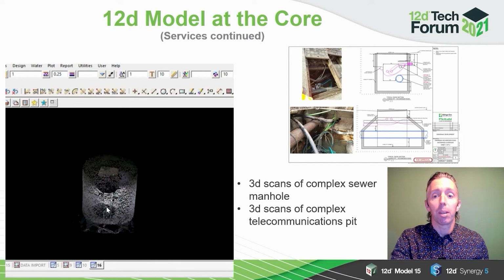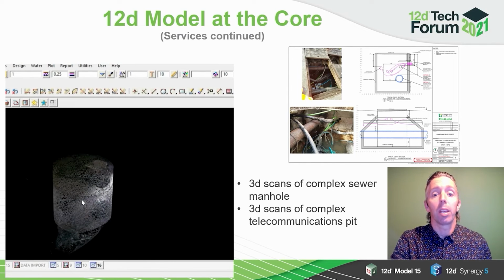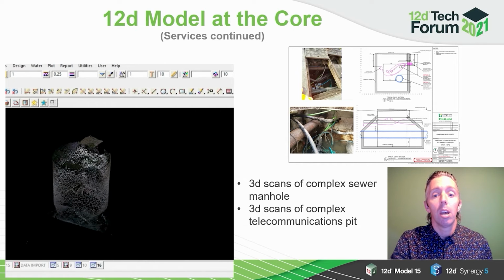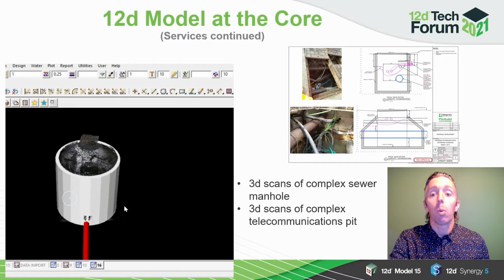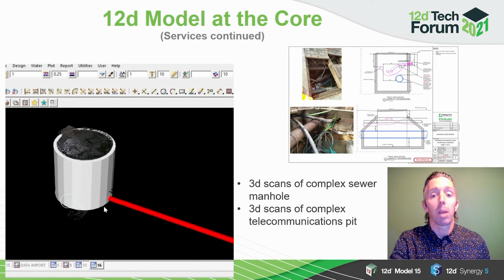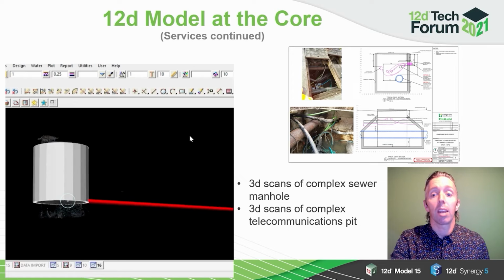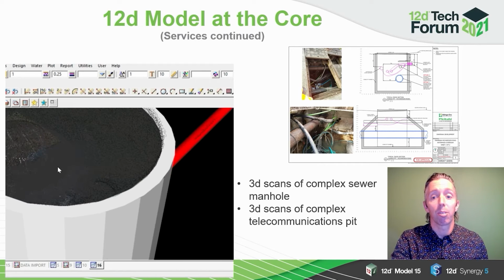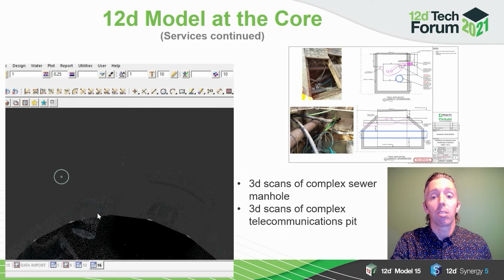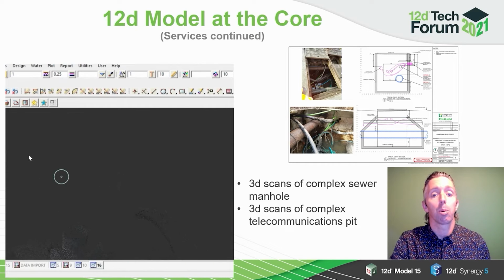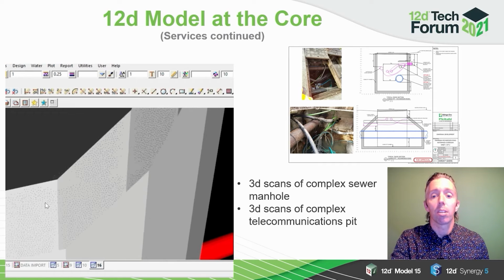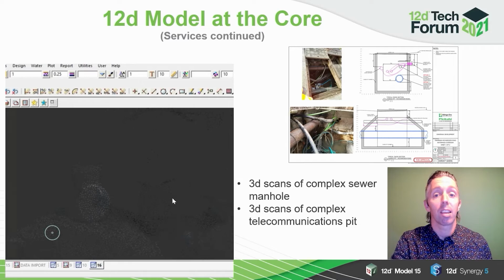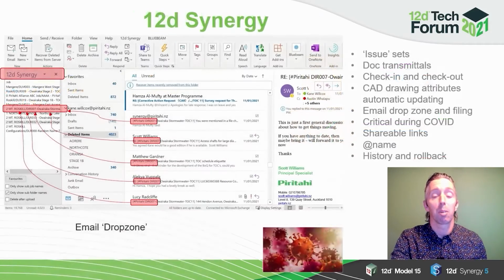With Oaraka being a brownfield development, we had to come up with some complex services that we needed to alter. Two are shown on the slide. One is a transmission sewer manhole, and for safety reasons we cannot enter, so we used a 3D scanner and created a 3D surface. In this short clip, you can see the complexities with internal dropper pipes and how priceless having the software is so that we can accurately and safely determine the invert level of the pipes.